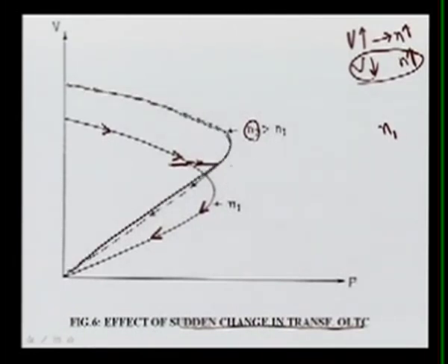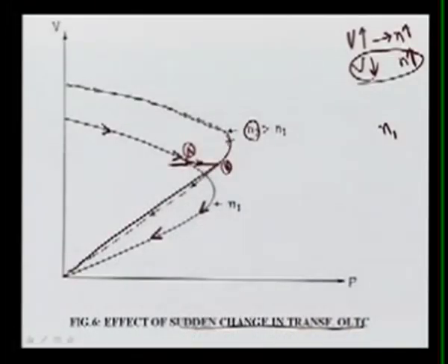What it shows is that after changing from here to here, point A was stable, but here it is going to point B, which is unstable in the sense of voltage stability. Okay, why? It is less than the nose point and is below this. So this portion from here to here is the unstable zone, and only this upper portion here is your stable case. So you can say a sudden change is also very dangerous, and it may lead to your unstable